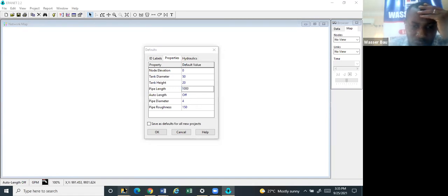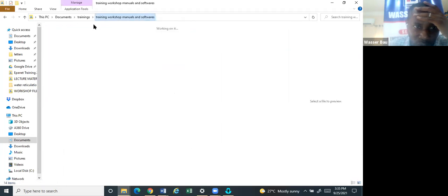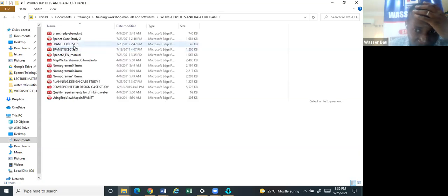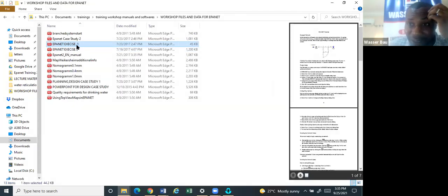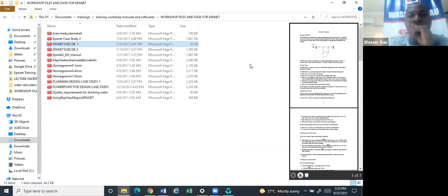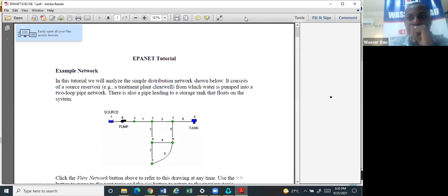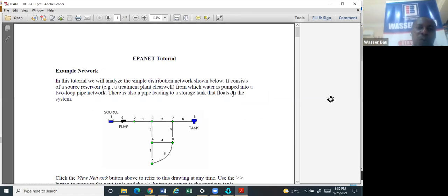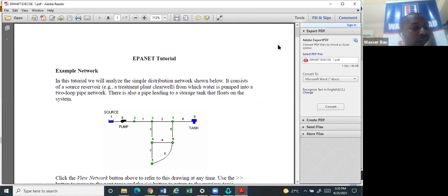Why? Because there's a tutorial in our material that I want us to first do. So go back to your material. You go to workshop files and data. You will see EPANET exercise 1. Open it with Adobe. EPANET exercise 1. So look at this network. This is a simple network. We're going to use it.